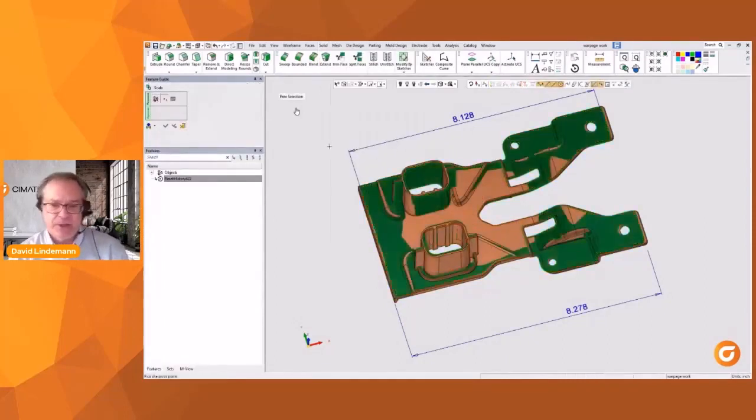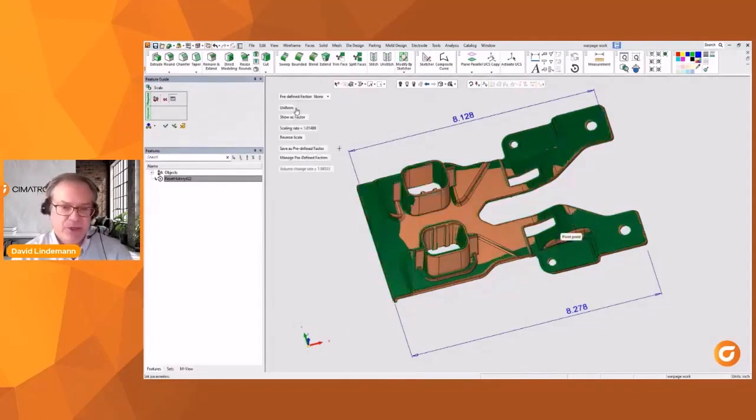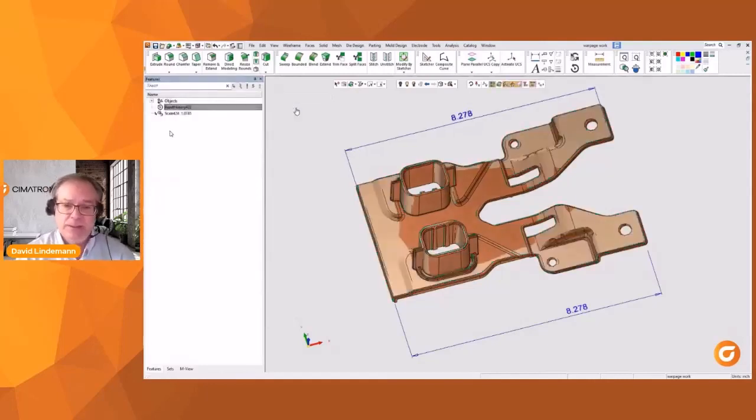With these two dimensions, though, I just simply divide one by the other, and that gives me the equation to know how much the shrinkage, that shrink factor, is involved. And from there, I can now expand the STL, scale it, so that it matches what's happening with the part. To get super specific, we can do it differently in the X and Y direction, Z direction as well. All right, so now I'm fairly confident that those parts are much more even in size, minus our shrink factor.